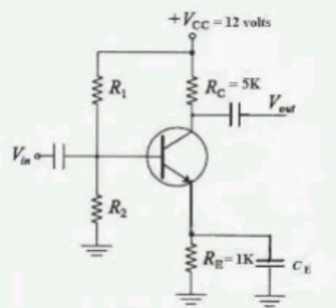A series resonant network consists of a 50 ohms resistor, a 4 millihenries inductor and a 0.1 microfarad capacitor. Calculate values of omega naught, f naught, Q naught, bandwidth, omega 1, omega 2, Z in at 45 kiloradians per second, and the ratio of magnitude of the capacitor impedances to resistor impedances at 48 kiloradians per second.